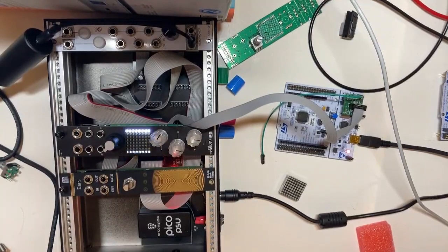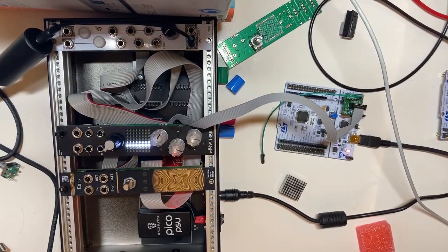So I now never use ADC3 from pure superstition. I just use ADC1. But it's got 16 channels, so I mean, you know, still pretty good. And we're using 7 of them. So I go to analog, I go to ADC, and you can see that it's basically switched on the first 7 channels for me. Now, there's so much flexibility on the ADC.